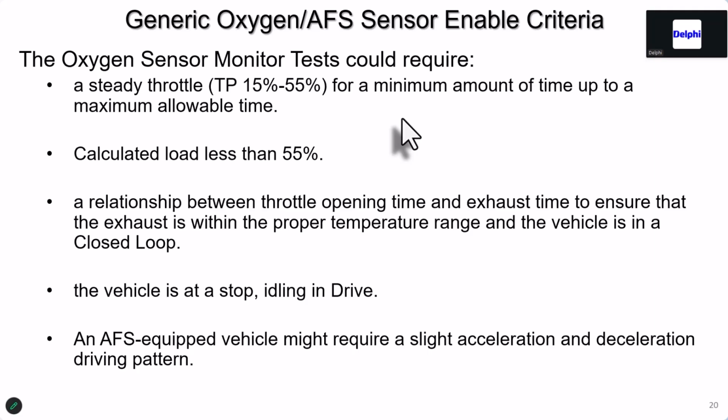The most important one, that third bullet: when you're trying to run an oxygen or air fuel sensor test, generally you're looking at about 2 to 3 minutes because there's a warm-up time. And think about yourself. If you were trying to warm up a catalytic converter in your stall, you'd either power brake it or take it up to 3,000 RPM and hold it there for 2 to 5 minutes,